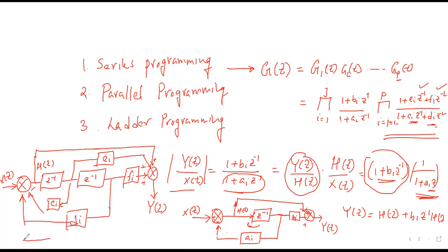Okay, so first order and the second order. So the whole pulse transfer function is to be decomposed as a series of first and second order sections. In this way, the error that is arising because of the quantization of the a_i's and the b_i's can be minimized. And if you look carefully, you don't have to actually follow the steps every time. Rather, just by looking at the pattern, you will be able to find out the way how to design it.